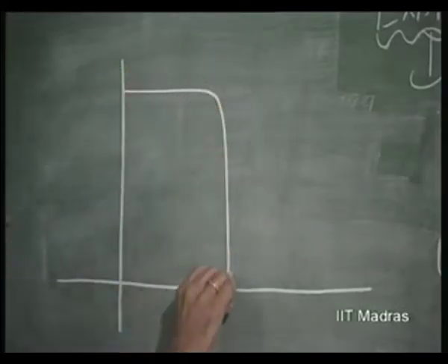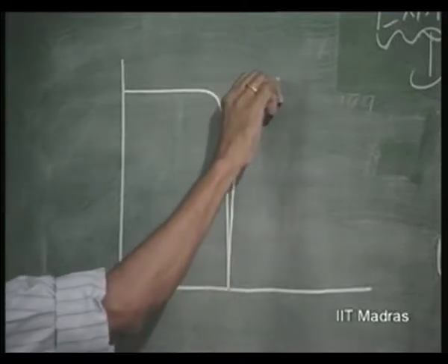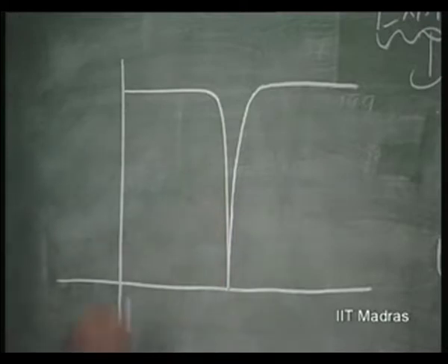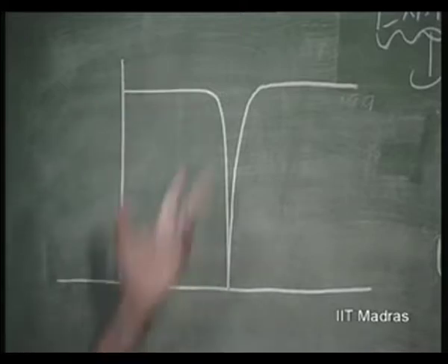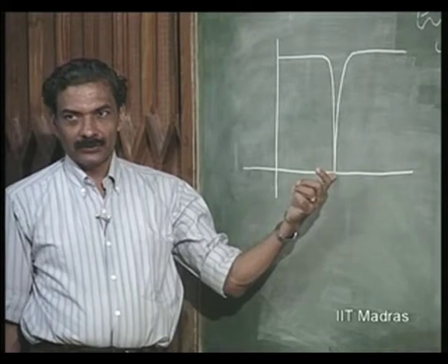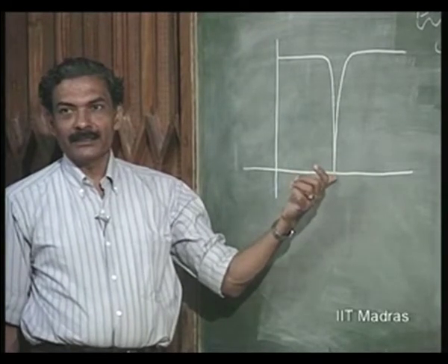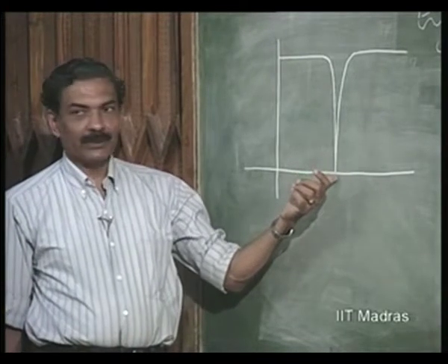Output should go to 0 only at a specific frequency. Right? It should be as constant as possible at all other frequencies. This is what is called a notch filter. It should go to 0. That can be done only by zeros, because zeros by definition indicate that transfer function goes to 0. So, I have to locate a finite 0 in my transfer function,